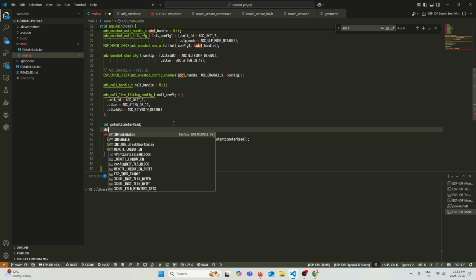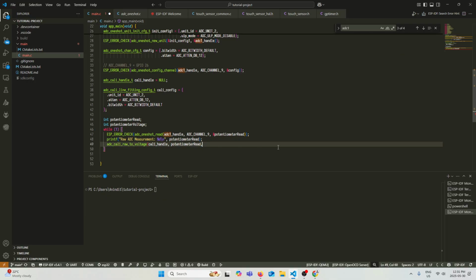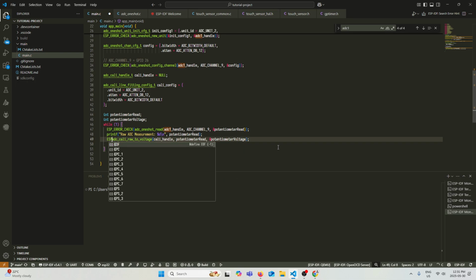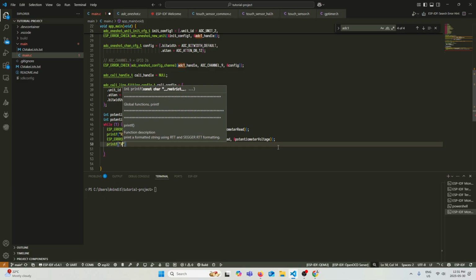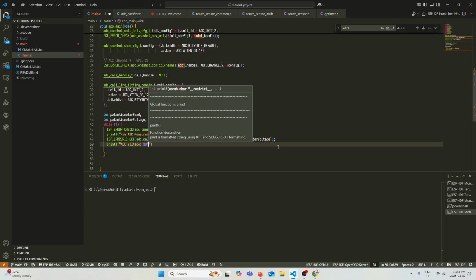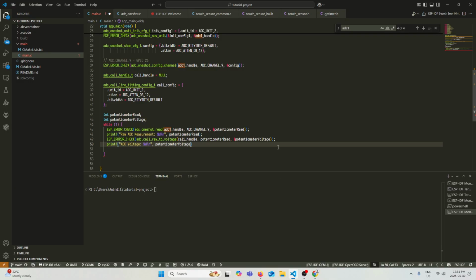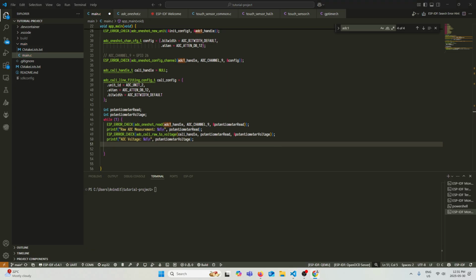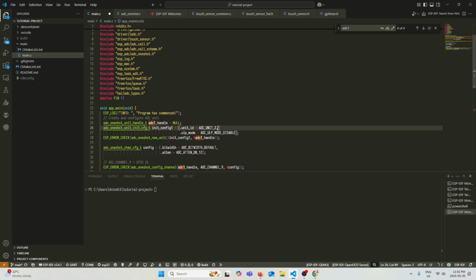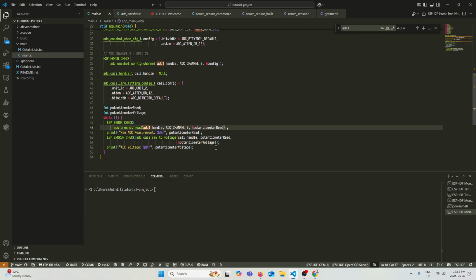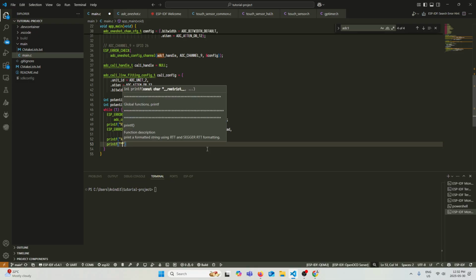Okay, and so let's just, good. On the ESP32, we can see that when we rotate the knob, the value displayed on the terminal also changes. The value of the raw reading ranges from 0 to 4095, which is also when we can no longer change the knob to either the right or left side. The maximum voltage level after calibration seems to be 3.1 volts, which makes sense considering that we give 3.3 as the source.